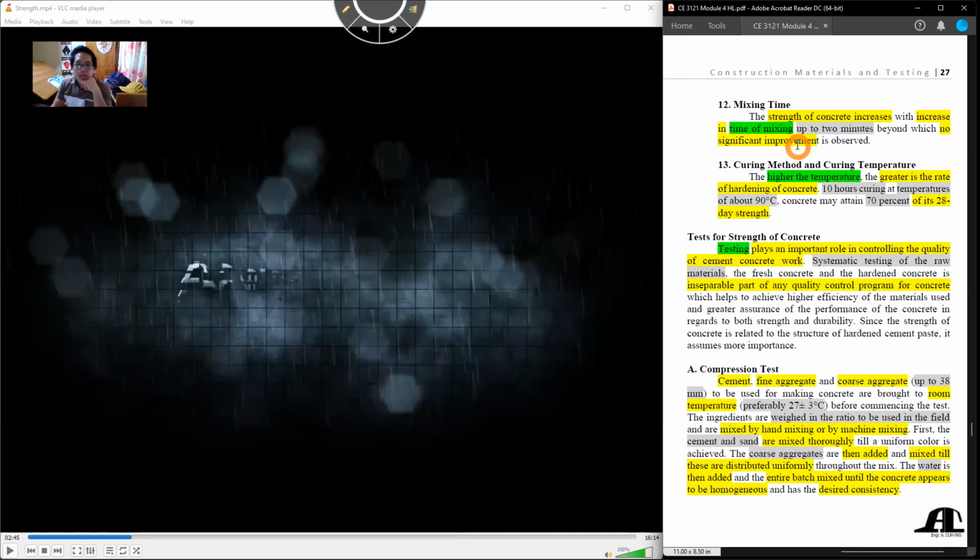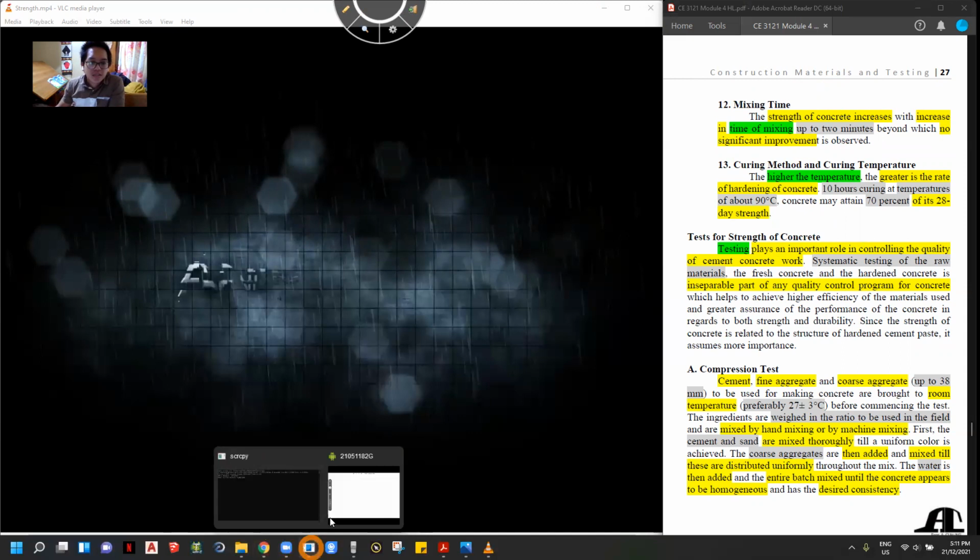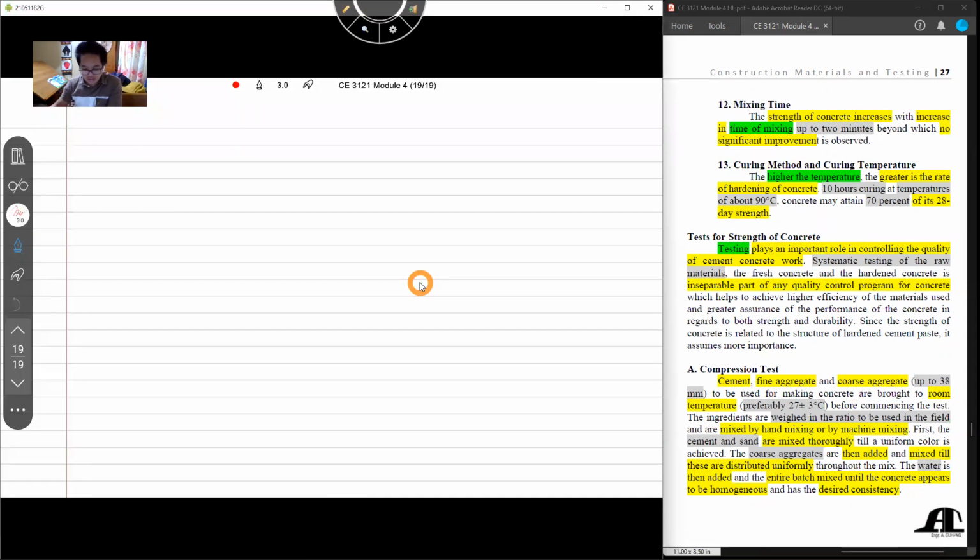Then curing method, class, and curing temperature. The higher the temperature, the greater the rate of hardening of concrete. So 10 hours of curing at about 90 degrees Celsius. Okay. So let's summarize, class, what we discussed earlier.